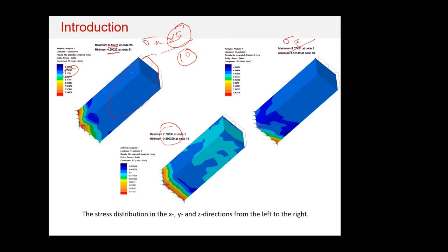So you have been doing the finite element analysis, and the cantilever doesn't have to be parallel to your direction. It's at some angle with your direction, and you get values for sigma x, sigma y, and sigma z. How do you know what is the dominant stress, and how do you know that you get the maximum possible stress to design for as a designer? And this is a question I'm going to ask you. So do you have an answer for that?